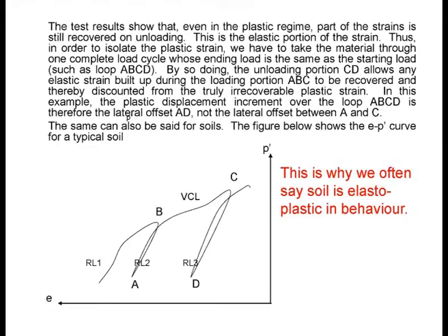This is not a very good drawing. I couldn't use the software very well, so it came out a bit crummy. Basically, RL1 is the recompression line at the start. Supposing you got a sample starting here. You load it, you follow the recompression line. If you unload along this recompression line, you will come back along here. Correct? This is the rule of the thing.